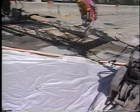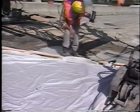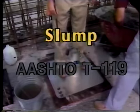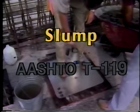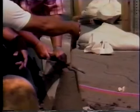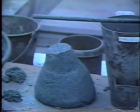Now, the air temperatures during concrete construction are also important. The high and low air temperatures must be monitored daily. Next on the list is the slump test, AASHTO T119. This is by far the oldest and most widely used test to measure the uniformity and consistency of concrete. Variations in slump generally indicate that changes have occurred in the properties or proportions of cement, aggregates, water, or admixtures.